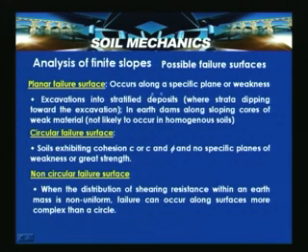Planar failure surfaces occur along a specific plane of weakness. This is the case when there is a weak clay layer, and the failure surface can take that particular path. It occurs in excavations into stratified deposits where the strata are dipping towards the excavation. Then the failure plane can be planar and in the direction of that weak plane.